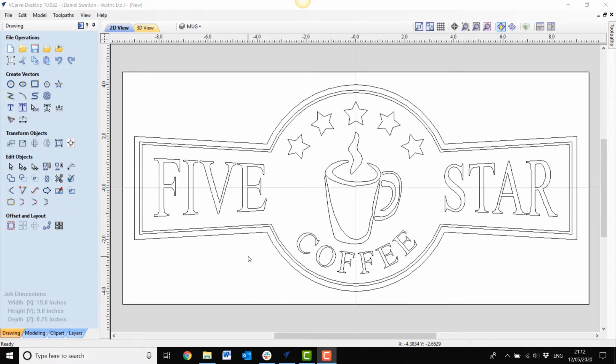And on question 2, can I work with third-party files? Well, the answer is yes again. You've got quick access to import a vast array such as the DXF, DWG and SVG. You've got the automatic tool to create geometry directly from the images, really the trace bitmap command. And of course, we've seen here today the ability to go from rough to smooth using the dynamic tools for tolerancing and smoothing. And if we do need to, we've got the complete control to drill down to individual vector nodes, if we do need to make any modifications.